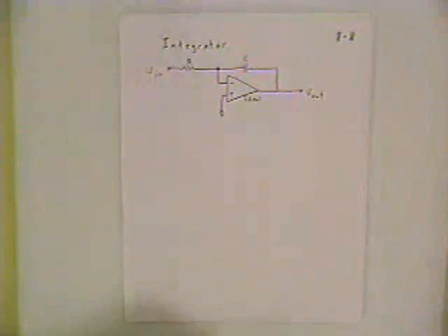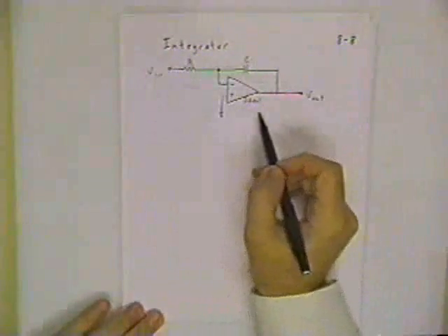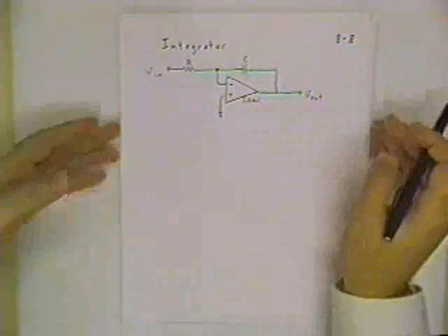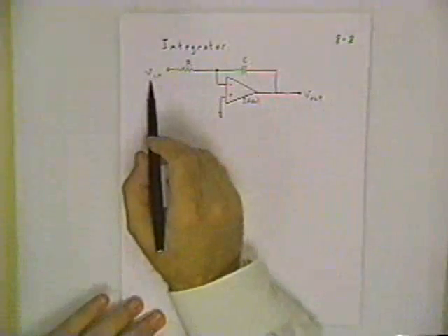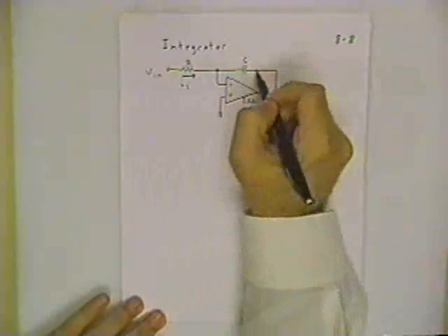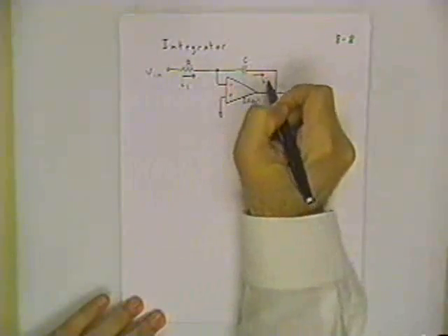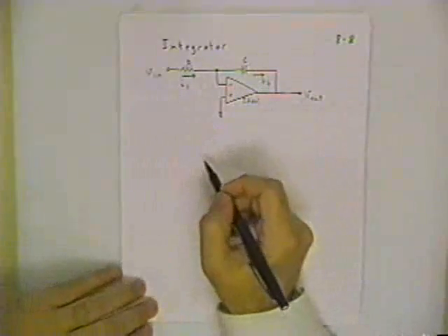Well, as one last example, let me show you the op-amp integrator and where it comes from. Notice that I'm involving the same basic layout as for the inverting amplifier. So one thing that we can expect is probably the output is going to be inverted with respect to the input. But the way we're going to decipher this problem is, again, just using the linear model for the capacitor and the ideal model for the op-amp.